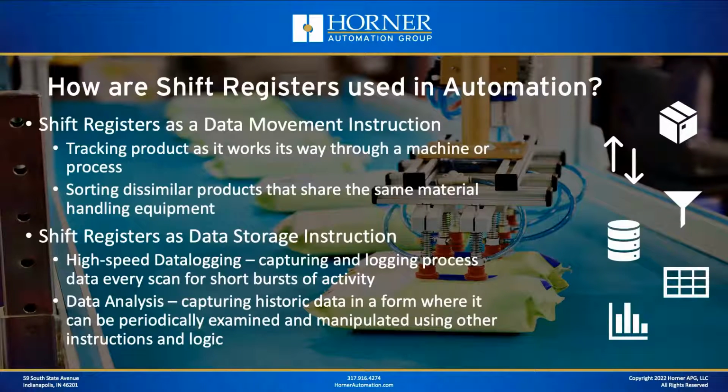Now, when we're using shift registers as data storage instructions, here's a couple of examples. First of all, how about for high-speed data logging? Maybe you want to capture and log process data extremely quickly, say every single scan, for a short burst of activity so you can analyze that data later.